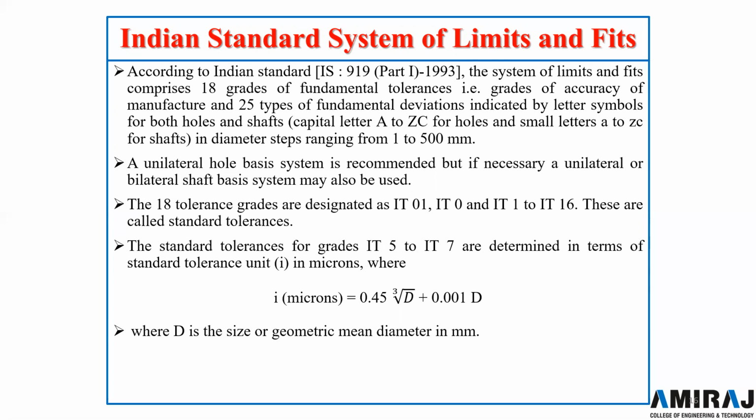Now the 18 tolerance grades: remember that the first two are IT01 and IT0. Then it starts from IT1 to IT16. So 16 plus 2 is 18 tolerances, and these are the fundamental or standard tolerances.